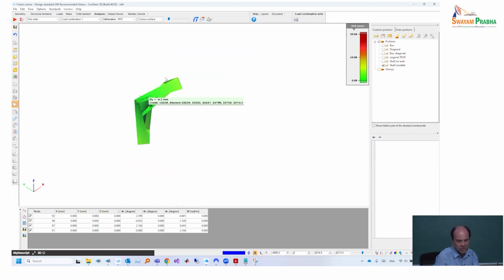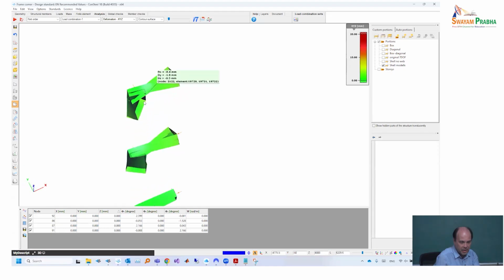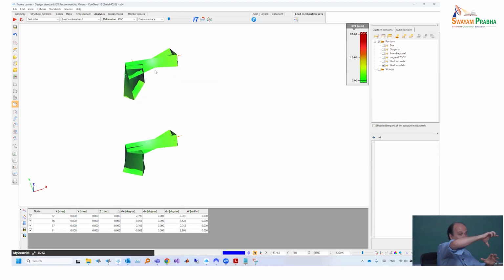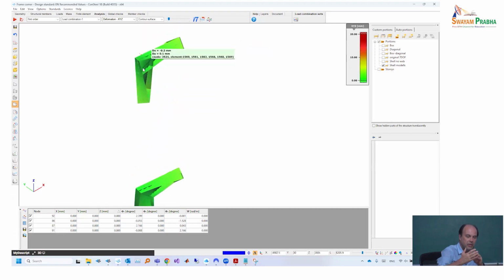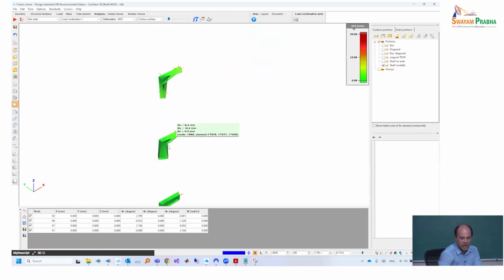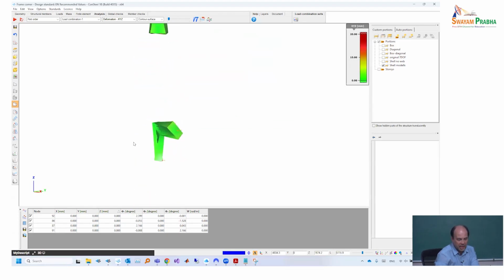And why? Actually, this can be very easily understood if you see that this flange comes into the zone with a certain rotation. That rotation continues into this plate. That plate moves to the right. It continues, it's a cantilever. Connected to this cantilever, they are moving together. Obviously, when they go out, the other must go inside, and this deformation already happens. This other is already more difficult to explain so easily, but this is a very rigid connection here.